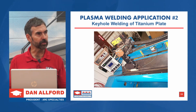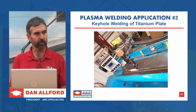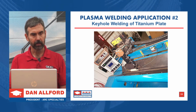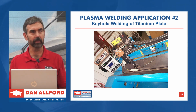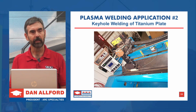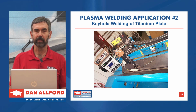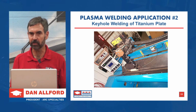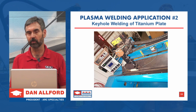So this one here that you see is just a seamer. It's a simple machine. It shows a wire feeder, but we actually keyhole the first pass all the way through the part, and we're punching all the way through a 1/4 inch piece of titanium, very reactive metal. And then the keyhole is formed as we increase the gas flow rate. And then behind the torch, the keyhole heals and we create a solid weld. It's a little bit low, so we go back in with a second pass with some wire, but it's an amazing process. So rather than creating a V-butt weld, we simply weld a square butt joint with no V at all.